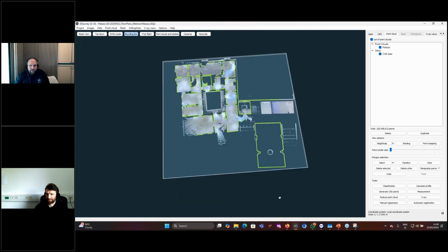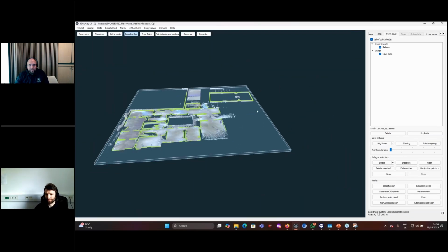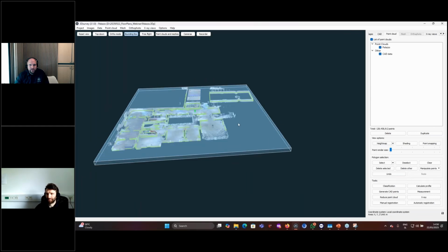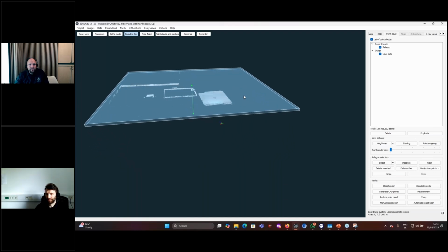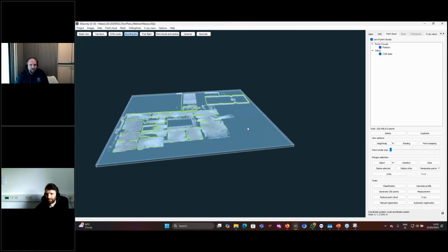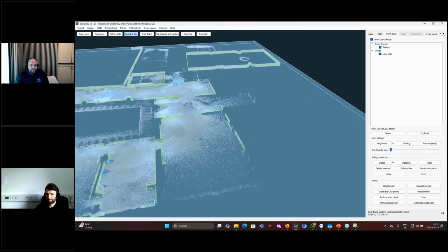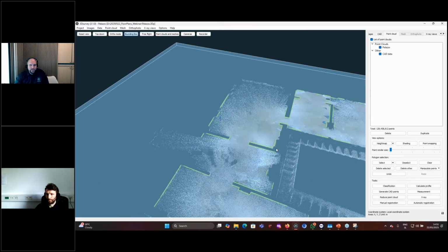And here are our automatically detected lines. So you know this trick, right? If you enable the bounding box, you make the bounding box thin like so. Then you right click on it, press Control on your keyboard, move it up and down, and you just move the whole bounding box up and down. It's a great tool to make the cross sections like that. And we can see that we did a pretty good job of extracting those walls that we had well defined in here.